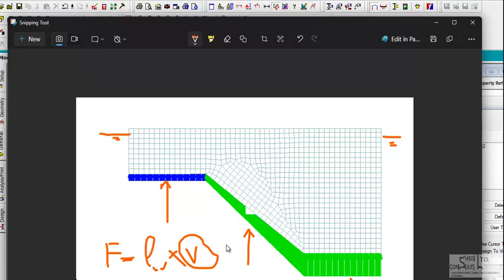To reduce the displaced volume, what you have to work with is either the area or the depth. If the depth of the swimming pool remains the same, you can control the area by reducing the area of the swimming pool. Once you reduce the area, the upthrust will reduce. Once the upthrust reduces and you thicken the base of the swimming pool, then you could have what's referred to as negative buoyancy. So the weight of the swimming pool will be greater than the upthrust, and the design will be satisfactory. Thank you very much.